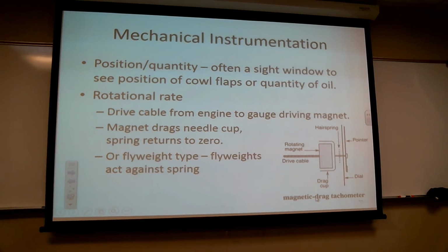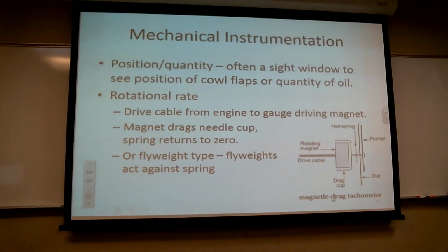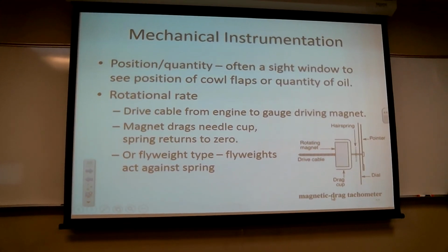The problem with these is, if I've got an engine out on the wing, and I'm a Constellation, so from the outboard engine to the wing root, I've got 45, 50 feet, and then from the wing root all the way to the cockpit, I've got 70 feet. That's a pretty long cable spinning round and round and round. So the cable technology here isn't going to work that well. If I could come up with an electrical way of doing it, it would be better.